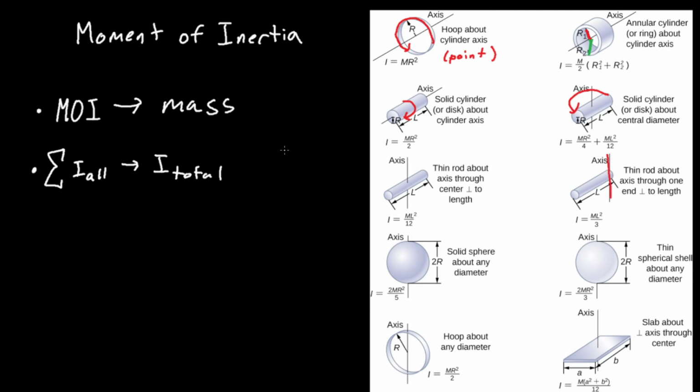How about the axis at the very end? So what if this guy rotates all the way around like so? Well, okay, I'm blocking the formula actually. Let's try to write this lower. But you can calculate this by just multiplying mass times length squared divided by 3. But how about this guy? Well, if you already understand how these work and all these pictures, move on to some problems. But if you still need some help, I will keep explaining.